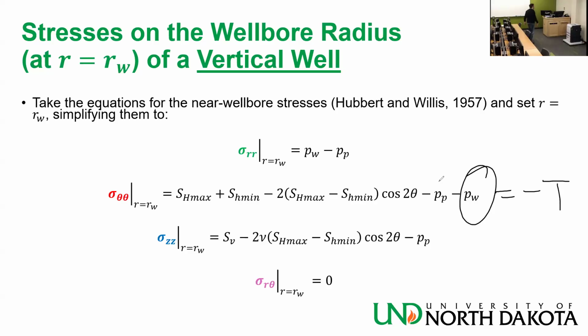You're going to get an expression for the wellbore pressure at which these drilling-induced tensile fractures occur. Basically, you are going to get a fracture initiation pressure indication, which we said is very, very hard to get, because fracture initiation pressure can vary from leak-off pressure to formation breakdown pressure.